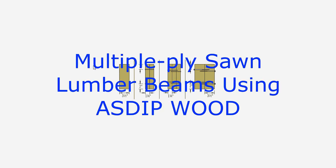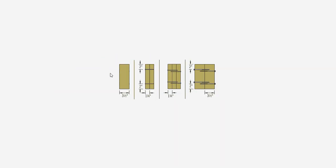Sometimes we have to design a wood beam under certain loads, but what happens when the beam size is limited for any reason? For example, if you cannot increase the beam height due to the space limitations in the building, or if the beam size is limited for availability in the market. What is the solution? Well, the solution is to add one more beam side to side.